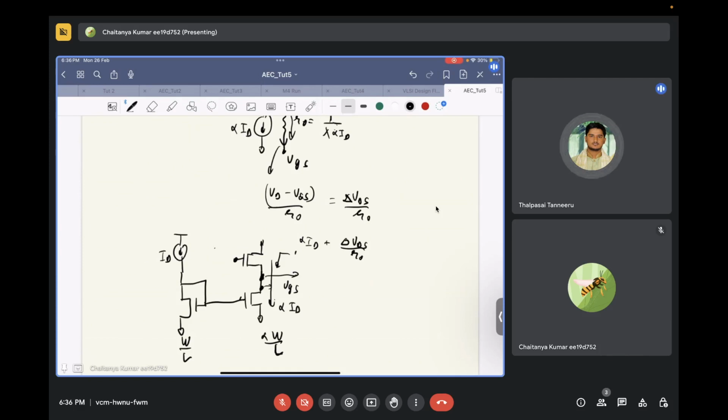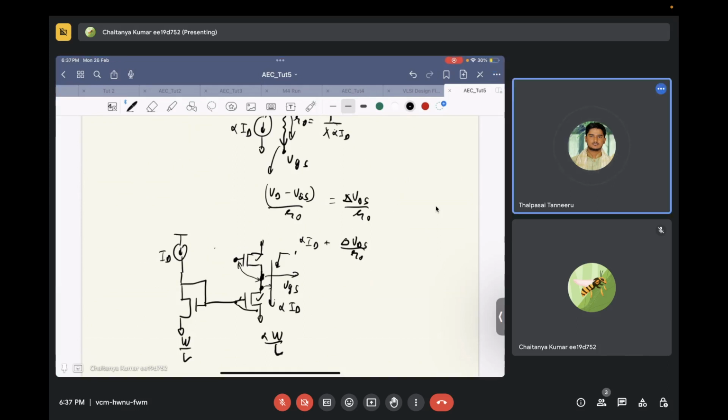Okay, now if this transistor and this transistor are nominally equal, then whatever VGS develops across this particular transistor will be approximately the same as the VGS that developed on the upper transistor, right? Yes, sir. So same gate voltage as same drain voltage. So it should be, sir, correct.